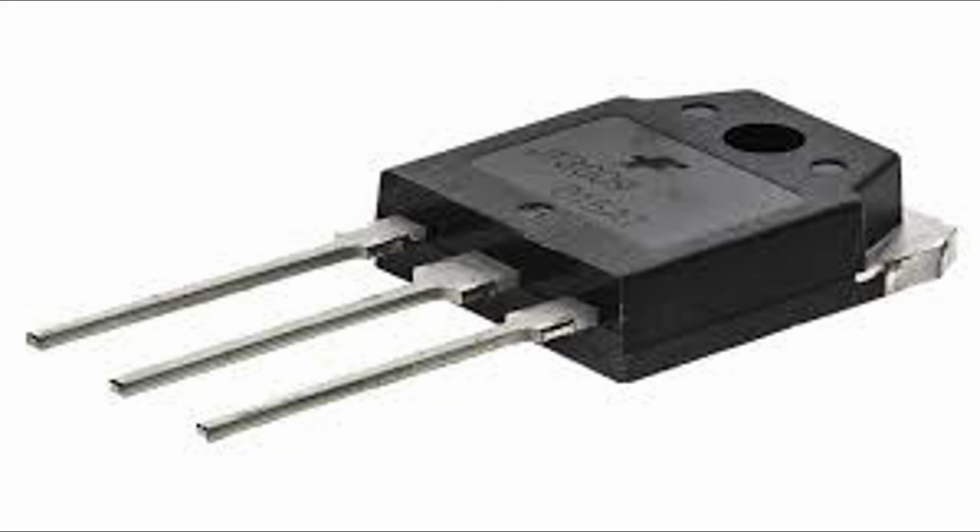3. Gate oxide layer. A thin layer of insulating material, commonly silicon dioxide, is placed between the gate and the channel. This layer prevents current from flowing directly between the gate and the channel while allowing the electric field to control the channel's conductivity. The thickness of this layer influences the device's performance, including its gate capacitance and switching speed.